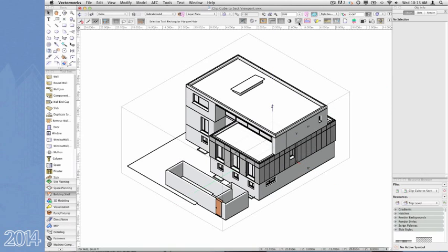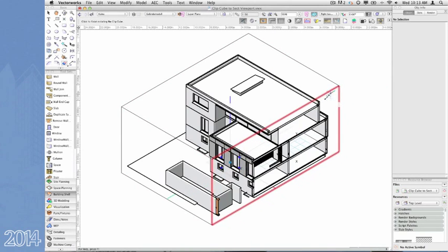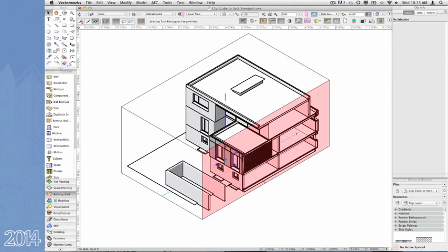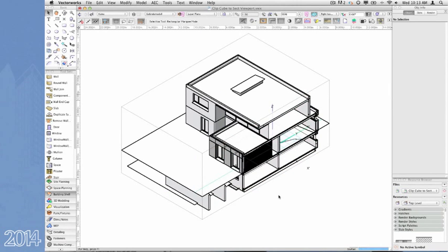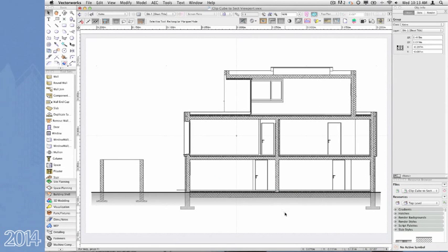Simply generate a Clip Cube view as before by setting the cube face as desired. Then right-click on the cube face. You'll notice a new option to create a section viewport. You'll have all the same properties and annotation capabilities from this section viewport as with any other section viewport on a sheet layer. For example, we created this ground line to embellish the look of the section.